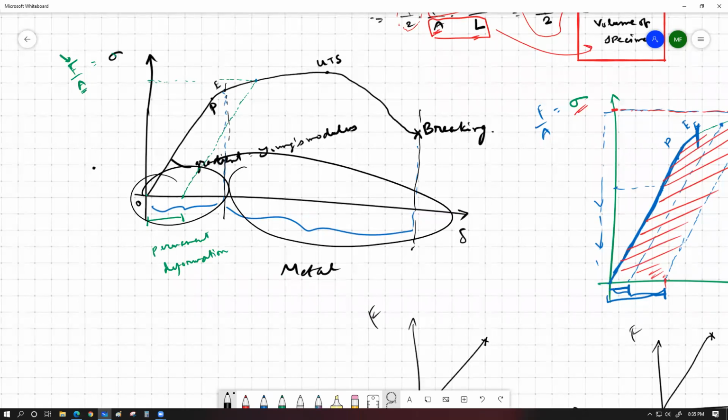So what is important is that ductility or malleability means objects which can show a large amount of plastic deforming capabilities. In that case, flour dough can be considered to be a pretty ductile material. But is it strong? Can it withstand a lot of force before it starts to deform? No, it's not strong. Do you get my point?